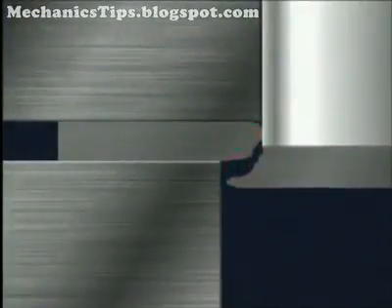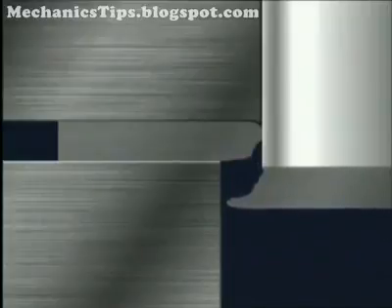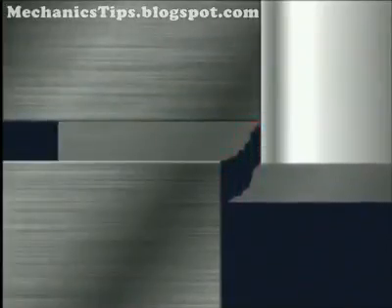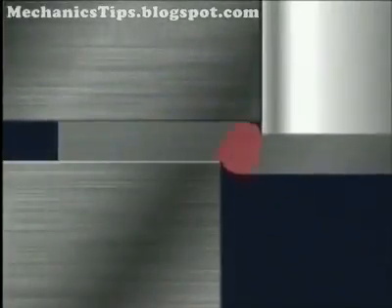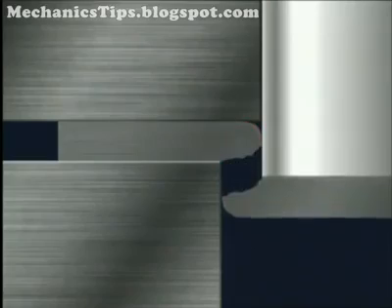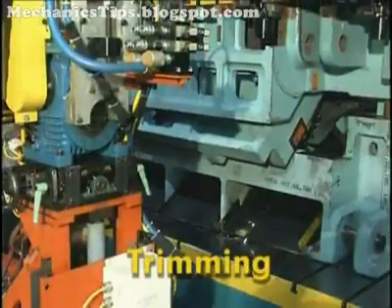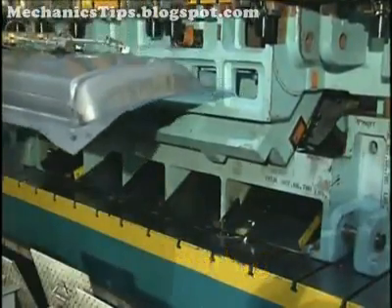Mild steel generally separates when approximately 1/3 of the stock thickness has been penetrated. However, when harder materials are die-cut, penetration by the punch may be less than 1/3 the material thickness, and softer materials may require almost full punch penetration before fracture occurs. After a part has been formed, a trimming die is utilized to remove the excess scrap metal from the workpiece.